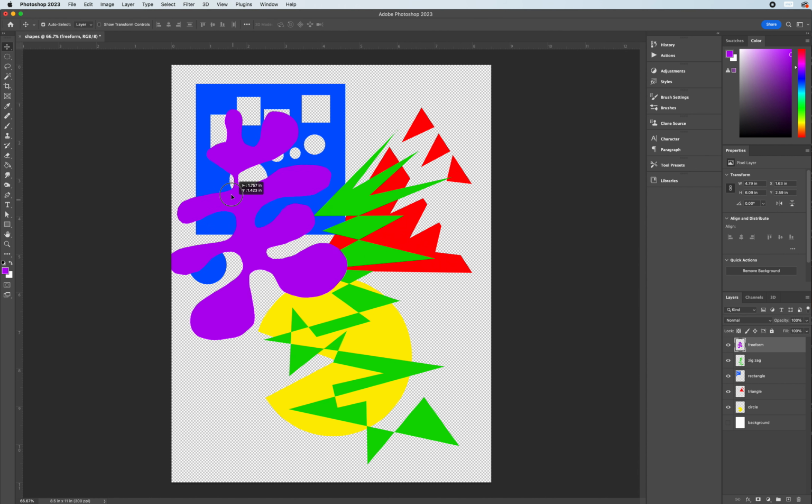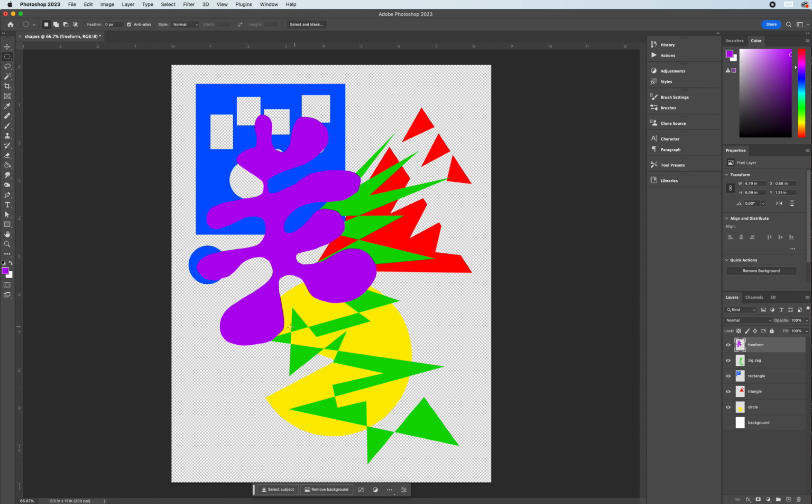Again, you can always use a combination of tools. If I decide that I wanted to put in a couple circles, I can draw in an area, and I could always move an object using the Move tool, or you can actually draw out multiple objects. So if I decided that I wanted to do a couple cutouts on every part or limb of this abstract shape, I can actually hold down Shift on my keyboard to draw out more shapes.